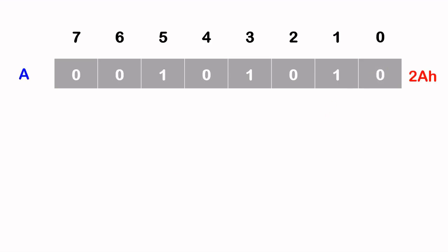Okay, so we now come to the parity flag, which is the P flag, and it's this bit, the least significant bit in the PSW register. Now the P flag will be set when the number of 1s in the accumulator is an odd number. This only applies to the register A or accumulator.